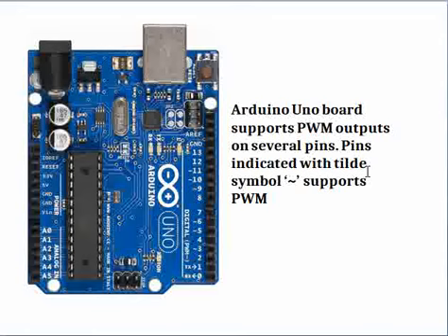So where do we use PWM? Basically, we use it in motor control applications, and you can use it for LED control. For example, if you want to glow an LED, a simple thing is you can just output your pin high and keep it high forever so that the LED glows continuously. But that is a very power consuming scenario.